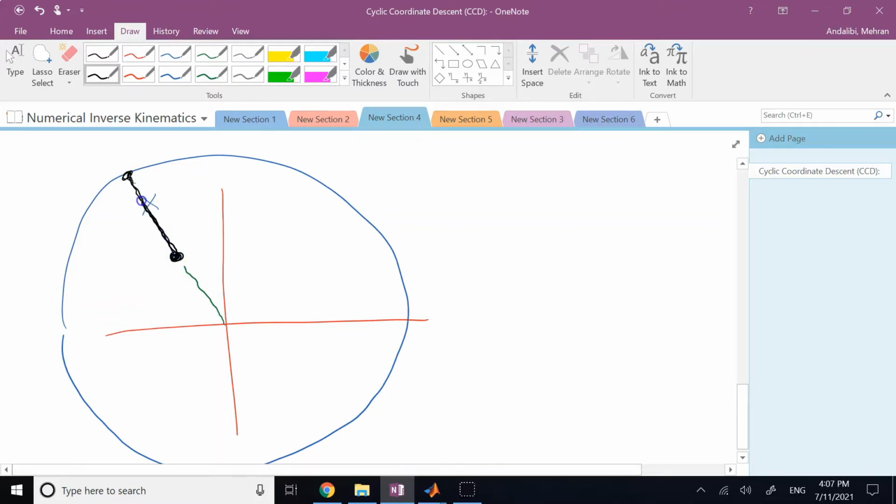So this one was your second member, and this green one was your first member. Your target was right on this line, and then it didn't move anymore. Although my end effector is not on the target, it did not update. You see that the robot could not move. Why? Because now the second joint, the end effector, and the first joint, the line connecting them, are all aligned with the line connecting them to the target.